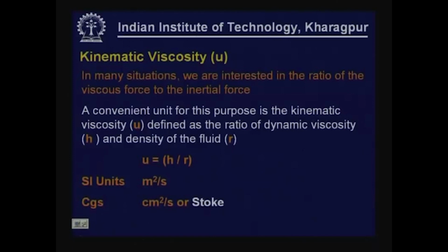While it is a very useful parameter to talk about absolute viscosity, it does not take into account the inertial force. In many situations, we are interested in the ratio of viscous force to the inertial force. A very convenient unit for this purpose is the kinematic viscosity.